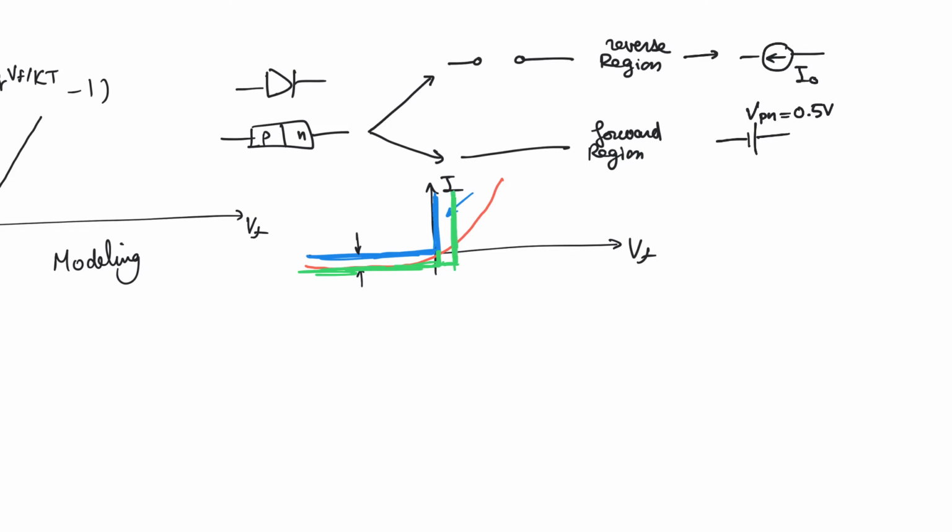So this actually is going to be pretty good when comparing to a diode current that looks like this, that increases quickly, right? It's going to be a little bit worse when it compares to a diode characteristic that increases with a slower slope in the forward direction. So perhaps what we are missing here is the slope. So how can we add a slope?